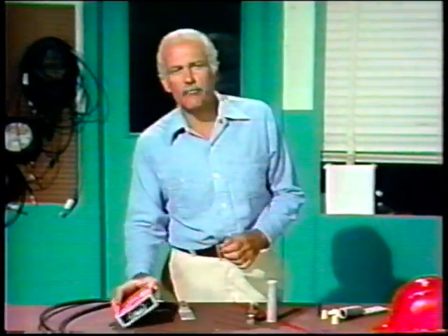Electrical tape is usually rated for voltage and environment. These ratings are not stamped on the tape itself. They're usually printed on the box provided by the manufacturer. The tape Bill is using is rated according to VPM, volts per mil thickness. The box says that the tape can withstand 69,000 volts per mil thickness, and that far exceeds the voltage rating on the conductor, so the tape meets the voltage requirement.